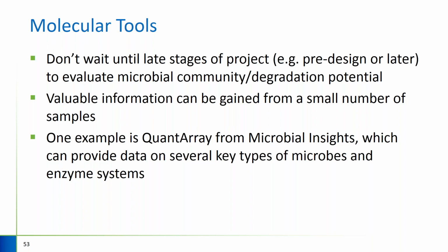So I've included one example here, this technique called QuantArray from Microbial Insights. There are others out there, but the idea is you can essentially add a sample on to a few of the locations that you're already going to be investigating. And you can learn a lot about the microbial community. Again, whether there are bacteria there that are known to degrade the contaminants that you have, whether they're completely absent, those kinds of things. And these samples, on a per sample basis, can get fairly expensive, but if you're only adding in 4 or 5 of these samples, it can really help you learn a lot about your site.